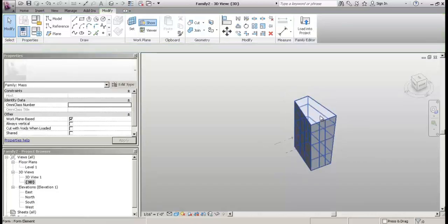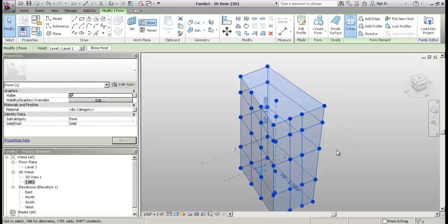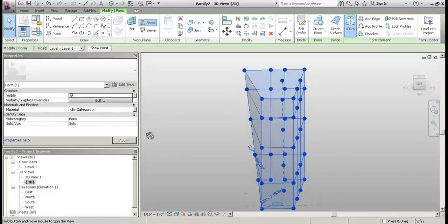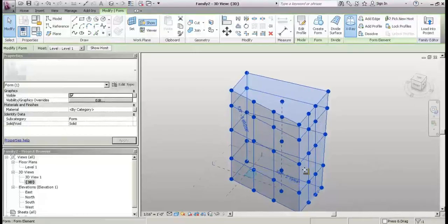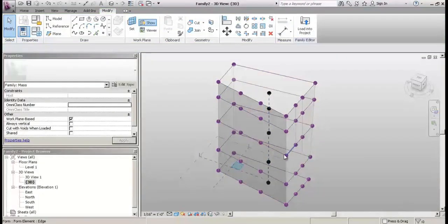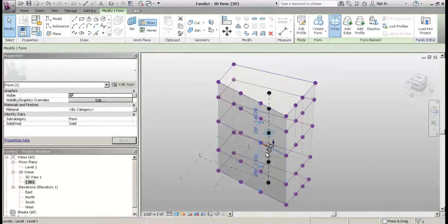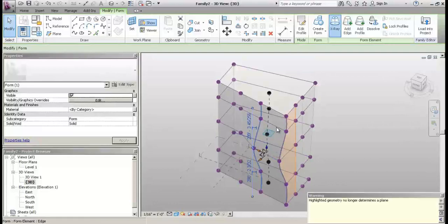The only way to get back at those, now if I select it I can see it, but I can't edit them. So I have this ability to then use X-ray view, right? And then I've basically made this three-dimensional matrix out of my box that I can now edit. Let's pull off of that so you can see the whole thing. I can actually edit individual segments now of this particular piece of geometry.